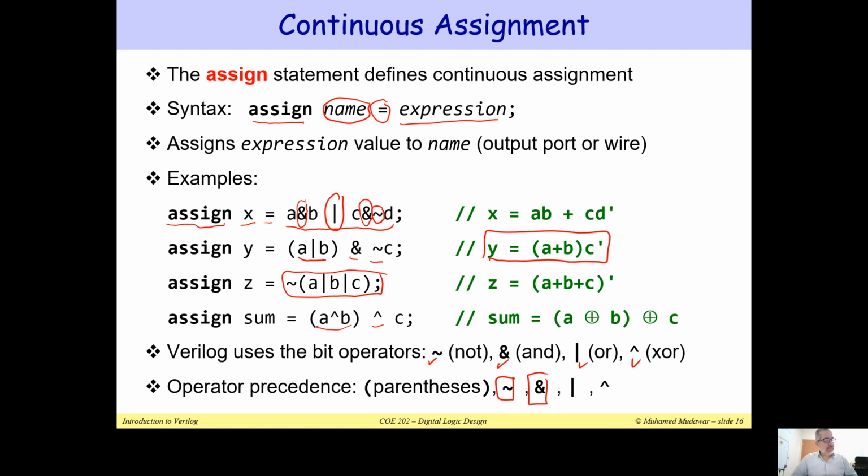So notice the XOR here. Okay, so we're using 2 XOR gates. So you can describe really long, complex expressions without having to describe them gate by gate. You can just write the expression. This is very useful in Verilog, and it makes the task of writing the description a lot easier when we use continuous assignment.